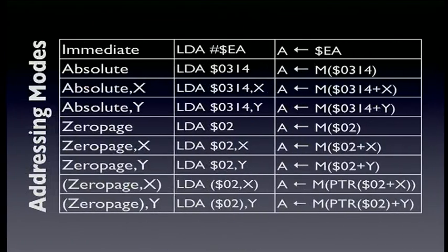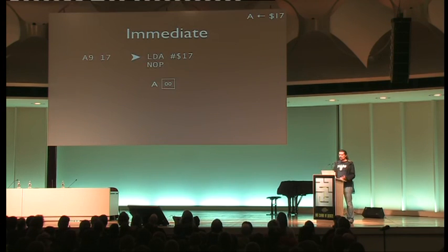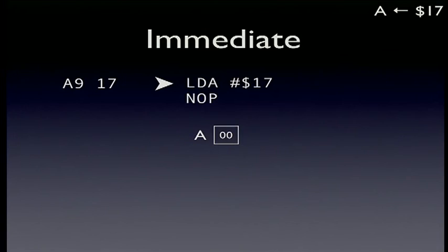So for all the general purpose instructions, these are the addressing modes that can be used in combination with these. There's an immediate addressing mode for using constants, absolute addressing modes, absolute and X and Y indexed. The same always with 0 page, and then 2 special ones for special 0 page stuff, which work around some other deficiencies of the design or some limitations of the design. Let's walk through the more important addressing modes for now.